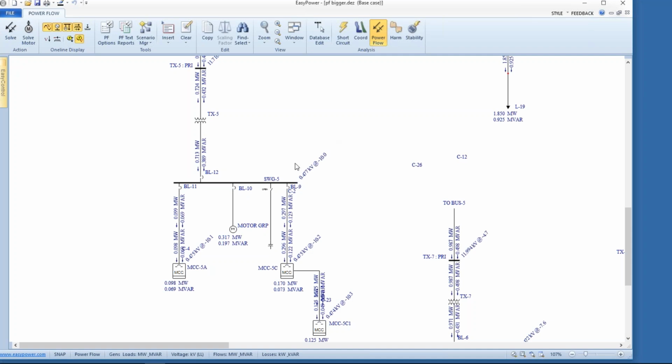Okay, so we noticed a couple things. First of all, we've eliminated our control violation, and what we see is that this voltage has changed simply because we put in the load tap changer as part of the transformer. And realistically, that could be improved if we put the taps, based upon how the transformer is set up, maybe even on the supply side.